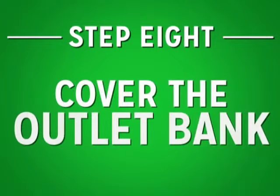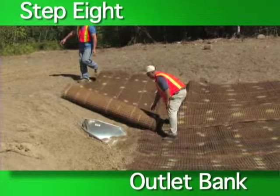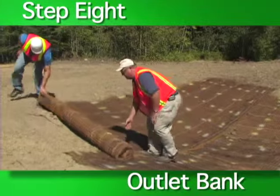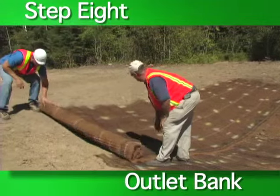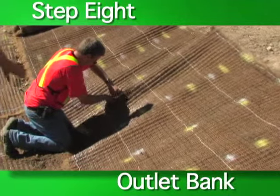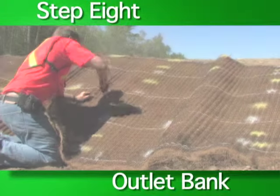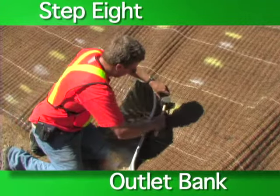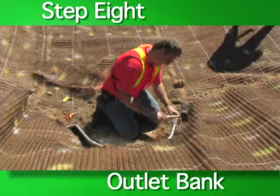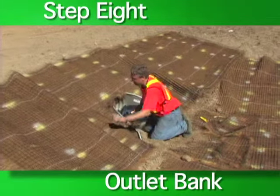Step 8. Cover the outlet bank. To cover the bank by the outlet, lay the RECP horizontally across the face of the culvert. Overlap the RECP over the trench at the base of the culvert. Cut out the opening of the culvert and secure the product around the outlet. Secure the rest of the RECP along the edges and staple the product using the pattern described earlier.